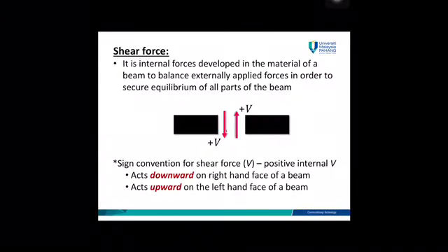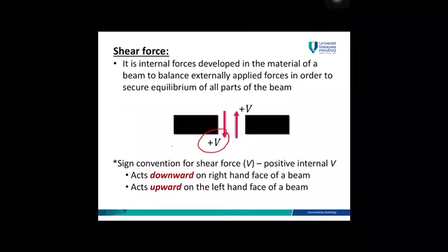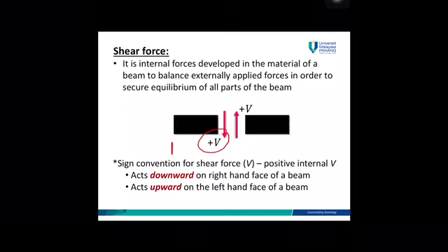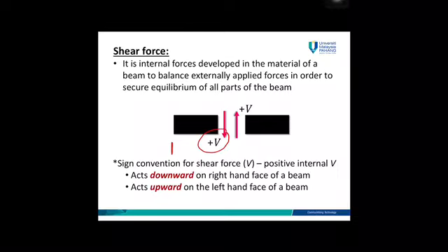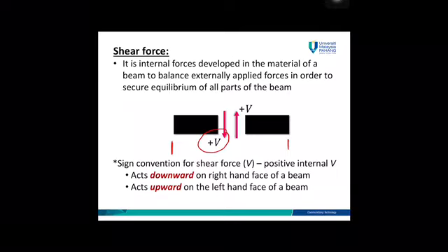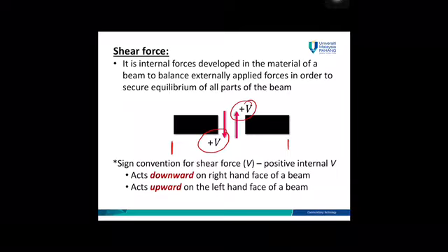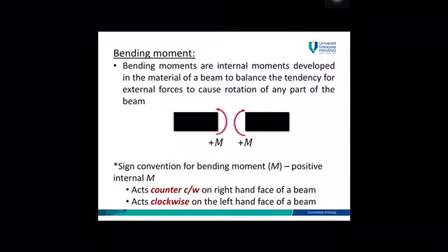The sign convention, if you take from here, which is from your left facing the laptop or your computer, then this is your left, then your V will be downwards, and if you take from right, then your V will be upwards. Same goes to the bending moment.